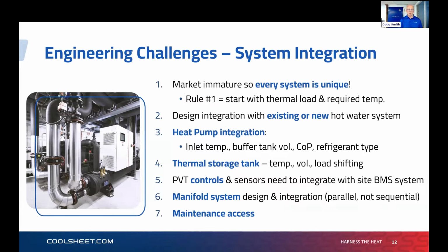You've got to start with the load requirements and the plant requirements. But all of these parameters effectively go into a good modeling exercise to dictate optimized sizing of equipment, tanks, buffer tanks, and varying different controllers. You can have an incredibly cheap controller if you're lucky for a site, maybe $600 to $1,000, depending on the complexity of your heat pumps. The complex control systems can be tens of thousands of dollars, of course.